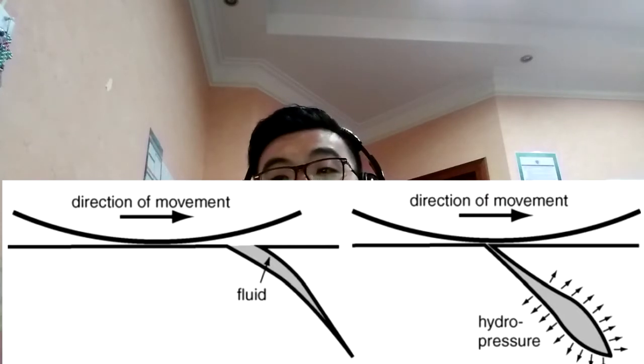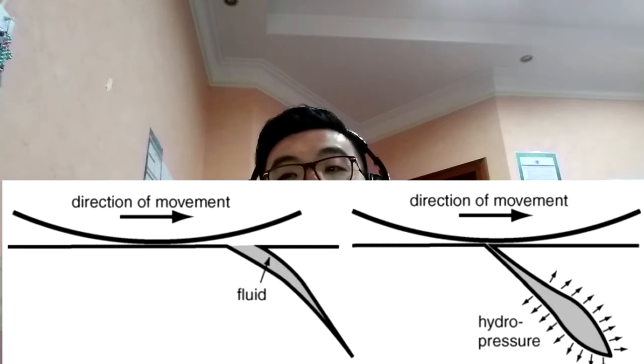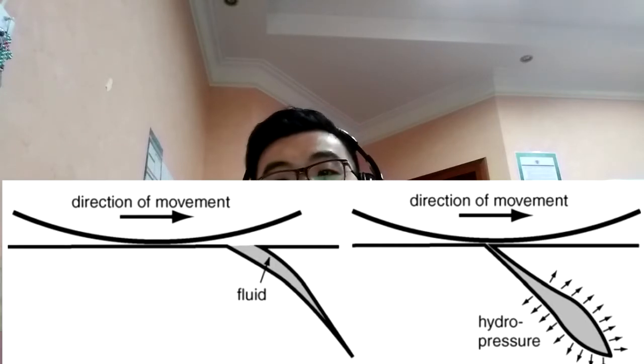As fluid enters the cracks on the rail initiated by shear and pressed by the rolling contact of the wheel, the contact pressure is transmitted hydraulically via the crack to the subsurface of the rail. The fluid is then entrapped and pressurized inside the crack, which results in the generation of squeezed film pressure. A rough surface has high asperity, which could provide a better grip than a smooth surface. Therefore, greater surface roughness gives a higher maximum coefficient of traction to a wheel-rail contact.